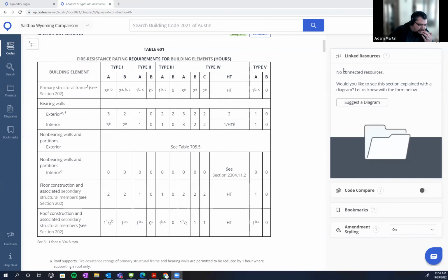Something that was brought up to me recently that I didn't really internalize until now is that if you look at the building code, you guys see it on the screen? Yeah. If you look at the mass timber types, it's type 4, A, B, and C, right? These are at the minimum, type 4C is equivalent to type 1B in its fire ratings.